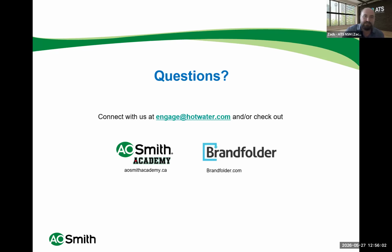I think that's a pretty easy answer. That's in the sizing guides. That's in the ASHRAE guide, right? Those different applications have a dictated peak demand period. Is that correct? Yes. So for apartments, for example, after you're following through the step by step going to pro size, there is a button that asks you about your low, medium, and high peak demand. There's another little button beside it that you just put your cursor over, and it will define what is considered a low, medium, and high peak demand.